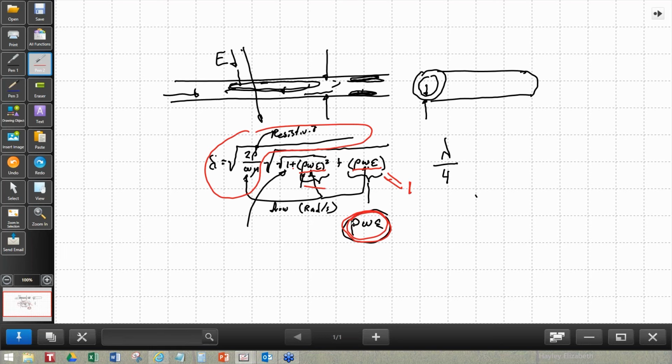In general, most vias that we're talking about for gigabit type signals have some characteristic impedance and some other effects, but the skin depth is not getting to a place where it's really highly significant. When you get to terabit signals, it's very important. So that'll give you a rough feel. Again, you can do the calculations.